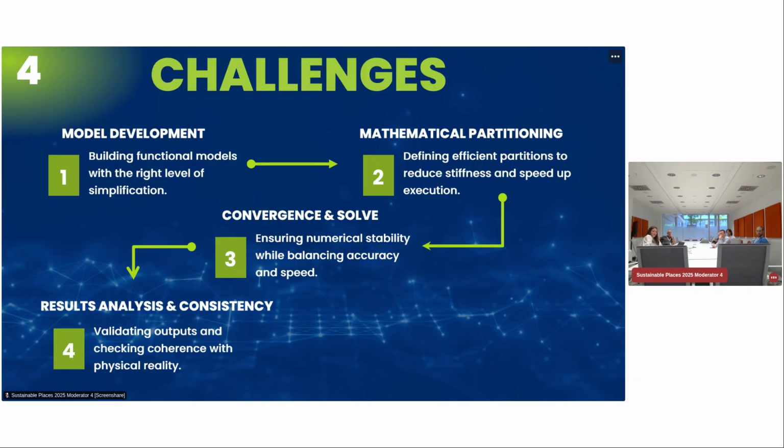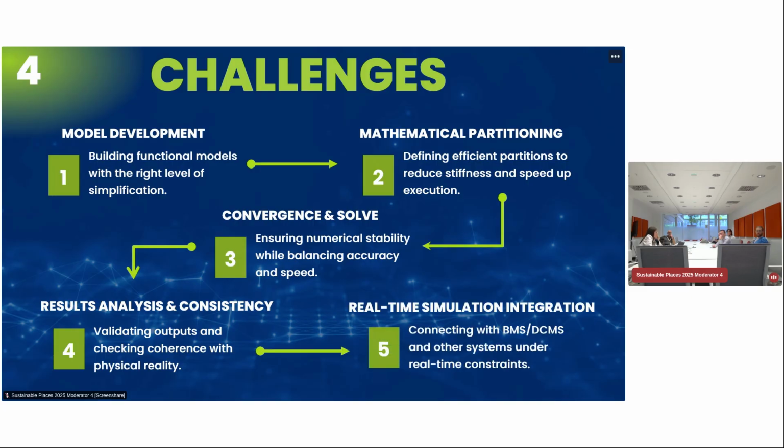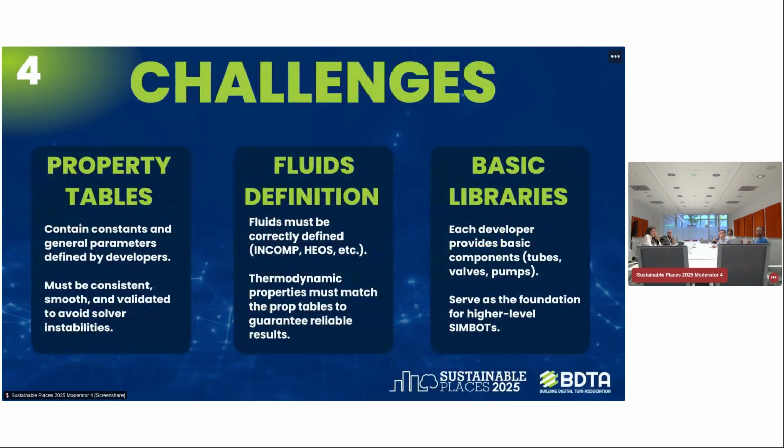Okay. Results analysis and consistency: verifying results and checking coherence with physical behaviors. And finally, real-time simulation integration: connecting the models with BMS or DCIM systems in real time. At this moment we are working on the OPC UA protocol, but there are others, and I don't know if this is the definitive protocol or not. Probably, but we don't know.